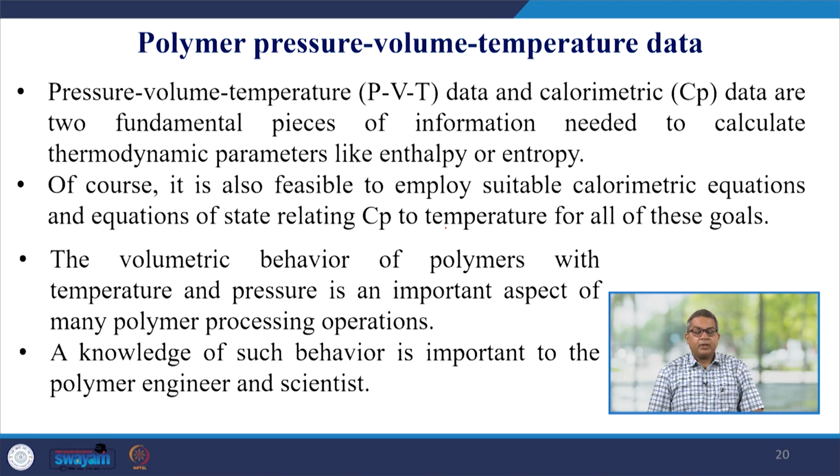So, let us talk about the polymer pressure, volume, temperature data. See, the pressure, volume, temperature, the PVT data, is very important. The reason is that if we need to define any kind of thermodynamic system, there are 8 different parameters needed, and out of 8, the pressure, volume, temperature are the only 3 parameters which you can measure directly.